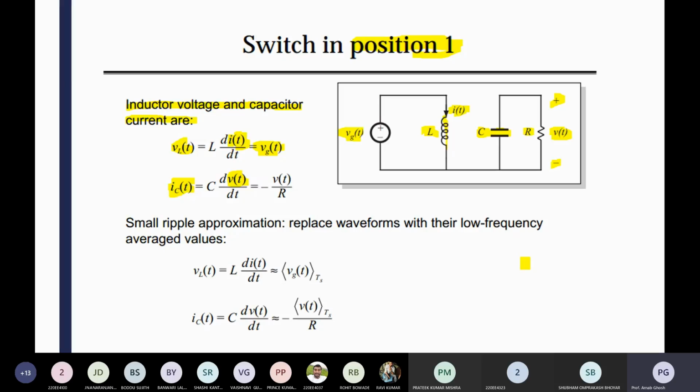Okay, so we have to know about it. In this case, I am taking a very simple converter, like the buck-boost converter. Okay, so there are boost, buck and buck-boost. Then you can go for the Cuk converter and the SEPIC converter, which are different. But up to these three conventional converters have two energy storing elements, so they have only two state variables.